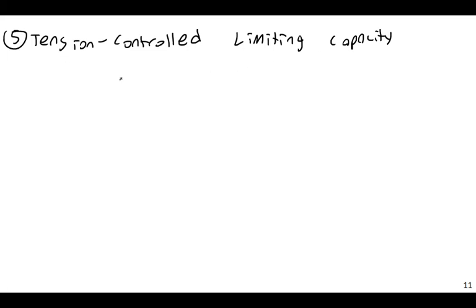In other words, we're going to assume in this case that the strain in the concrete is always going to be 0.003, but then we're also assuming that the strain in the tension steel, epsilon S1, is 0.005. That is the boundary of the tension-controlled range. So first, let's show the strain. It's going to look very similar to some previous cases.